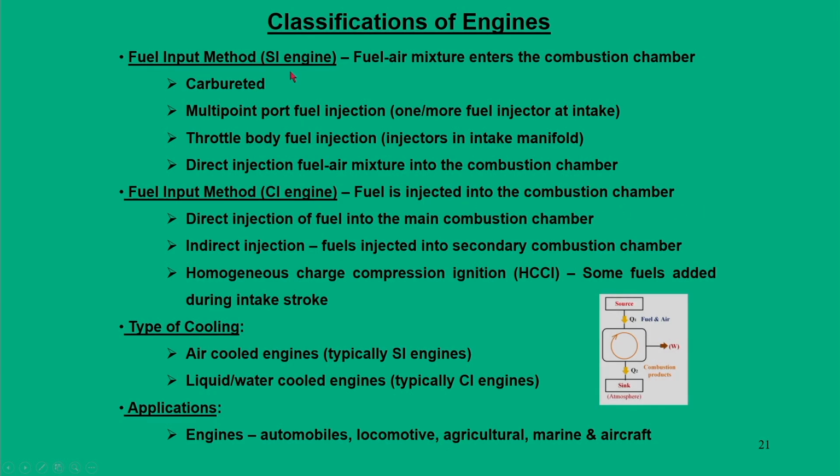And the last concept is the fuel input method. We said how air comes into the engine, now we will say how fuel comes into the engine. Basically there could be two possibilities, one for SI engines, the other for CI engines. A basic difference is that in SI engines the fuel and air mixture enters the combustion chamber together. When they enter they have to be mixed properly.